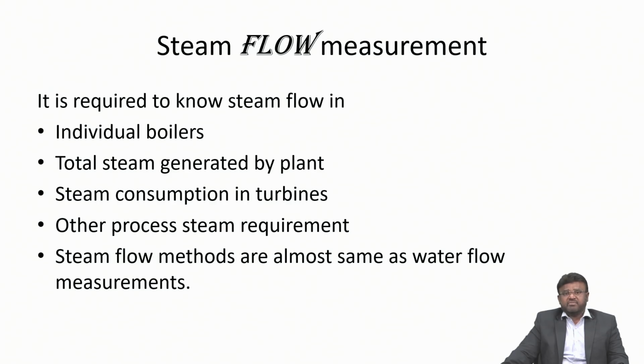In order to save fuel, rather than switching on every boiler every time, depending upon the demand of the pressure, we can start some boilers out of n boilers. If more power is required, more boilers need to be switched on. If less power is required, only a few of them can be used. So in this way, the steam bus does its work in selecting, in utilizing various turbines, or to which turbine it has to give the power.